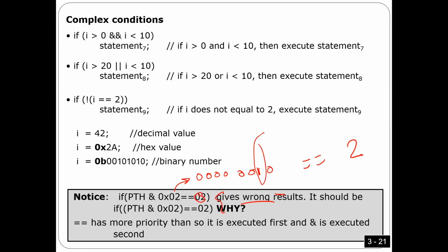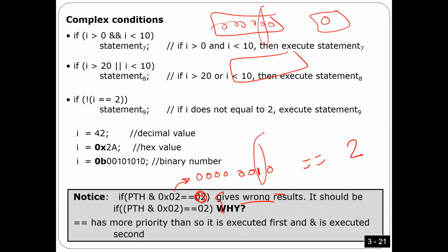If you put 0, that means the switch is connected, right? Because after you do this AND operation, you should get one of 2 values. You can get all zeros, and that means this bit is 0, okay? So if the result is 0, that means the switch is connected. Or you can get 0, 1, and everything else 0, which is number 2, and this means the switch is open anyway. So here I want to check for open, so I can do something like that.